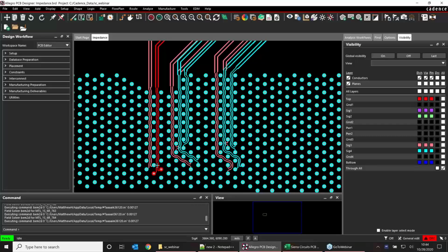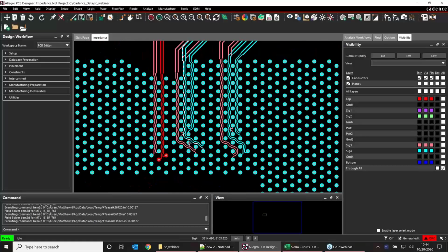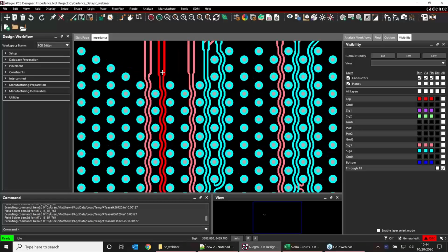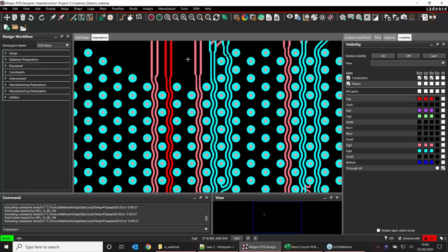The other thing that you're seeing in action here, in case you've ever wanted to do it, is something that we call snake mode. You can snake through this to get through areas that would otherwise be hard using traditional corners. Those might not be areas that you'd be able to escape out of using traditional techniques, so we have snake mode to get out of there. We have neck mode to make the traces a little bit tighter, and that allows us to escape our pattern. Then we can go out here, release those restrictions and go to regular routing mode, where we're going to be able to hit our impedances that we want.